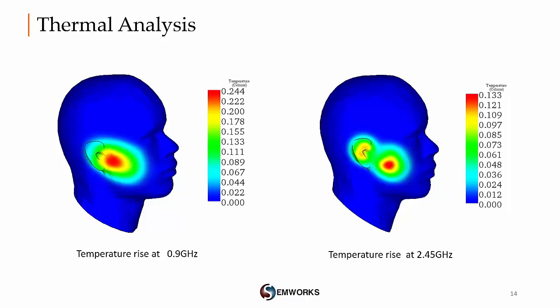As seen, a local temperature increase is obtained across the human head tissue near the cell phone antenna position. The thermal behavior follows the electric field and also the SAR behaviors, which are dependent on the frequency of the incident waves. It increases by 0.25 degree for the 900 MHz and by 0.14 degree for the 2.45 GHz, which are within reasonable limits and could increase more with time.